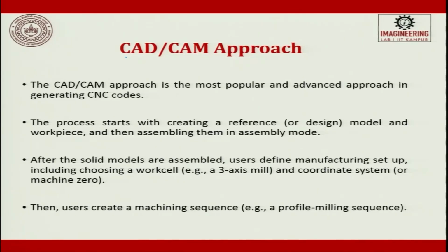So, the next approach is the CAD/CAM approach. There will be a demonstration on this topic by Dr. Amandeep Singh, but let us quickly go through what is covered here. The CAD/CAM approach is the most popular and advanced approach in generating CNC codes. Here we do not do it manually; the system itself will read the drawing, try to understand it, and give you the G codes and M codes. The process starts with creating a reference model and workpiece and then assembling them in assembly mode.